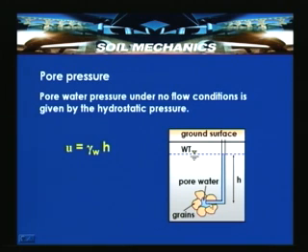So, this is the pore space which is filled with water, and the depth we are determining is h. Suppose we wanted to measure this; we have devices for measuring the pore water pressure at a certain depth below the ground surface. Here, h is the piezometric head we refer to, which indicates the pressure here.